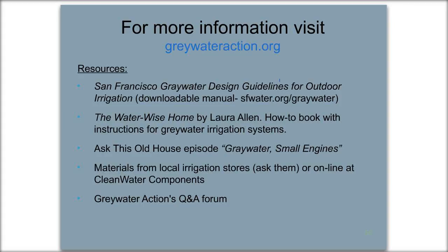I'm sure there's a way you could do it. I'm not imagining how it would work very smoothly to have it below the machine, other than tapping into the drain of the washer. And then you would be having a different kind of system, because you've tapped into the gravity flow drain, and you'd be having a similar system to the branch drain. To actually build a laundry to landscape system, you need the washer discharge hose directly connected to the valve to keep the pressure of the pump pushing that water through the system.